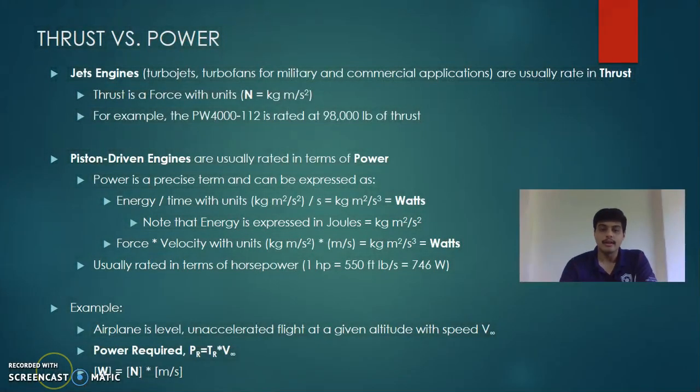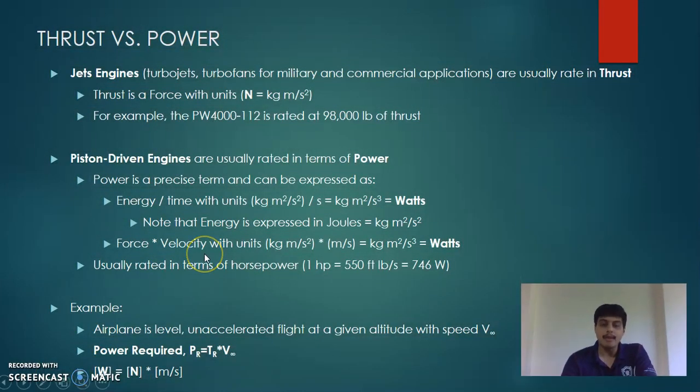What do we need in terms of our thrust requirement? You simply see that power required is thrust into velocity, and so it is Newton into meter per second. So it is a power rated engine that you will use, and if you use a power rated piston engine, you will have to specify what wattage is required by first computing the velocity and then computing the thrust required.